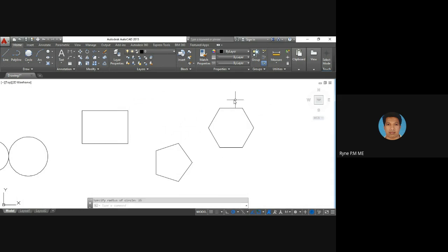You want to draw it inside a circle, means again you have the option polygon. You have 6 sides, so enter that, and give the center point here. Instead of circumscribed, I am selecting inscribed circle, so that now it is coming inside the circle. If you draw a circle of that radius, this pentagon is coming inside it. If I give 25 again, I get a smaller pentagon. Okay, hexagon. So these are different tools for drawing line, circle, polygon, etc.